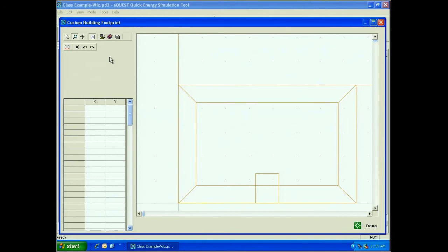We want to start drawing the vertices here, so I'll click on the arrow on the right side there, and I'll start in the lower left corner. Just click on that. And as I move my cursor away, you see that it has a blue dot with a plus sign in the middle. That's our vertex. When I have my cursor in the screen area up here, down below the picture, it shows the coordinates of where your cursor is.